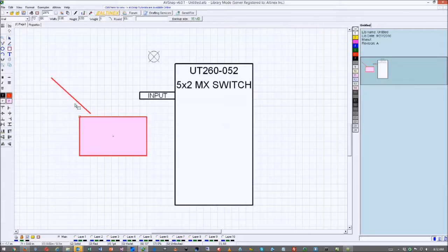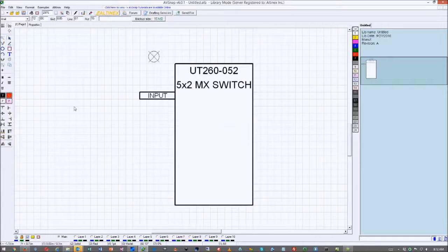And the reason I'm saying this is because some people say, why do my properties change without me doing anything? Well, if you play with any of these without anything being selected on the page, you are adjusting the default settings, okay? So I'm going to go ahead and change line to black and fill to white. And the same thing happens on the bottom. If you're changing the line type solid, black, and the size of the line, all of these will be reflected as default settings. So just keep in mind, if you're selecting something, you're changing the property for this particular object. If you don't select anything on the page, you're changing the default properties for the new object that you're going to create.